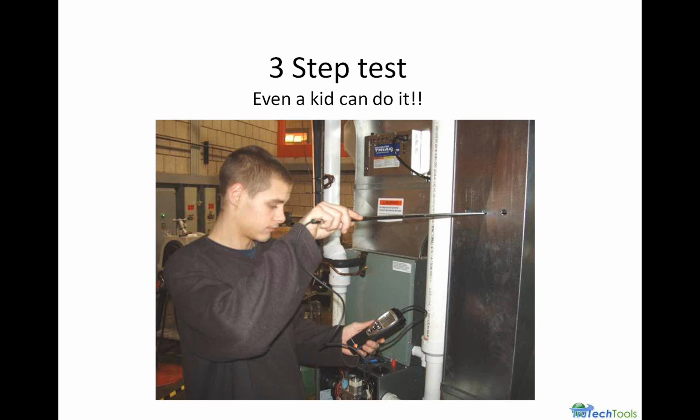Andy's using a vane anemometer to measure airflow. You can see his technique is very good there. The vane is nice and perpendicular to the airflow. He's measuring in a nice tall return air drop, and he's getting airflow on the system. He's measuring 3 points in the duct system because we're doing a traverse of the duct.